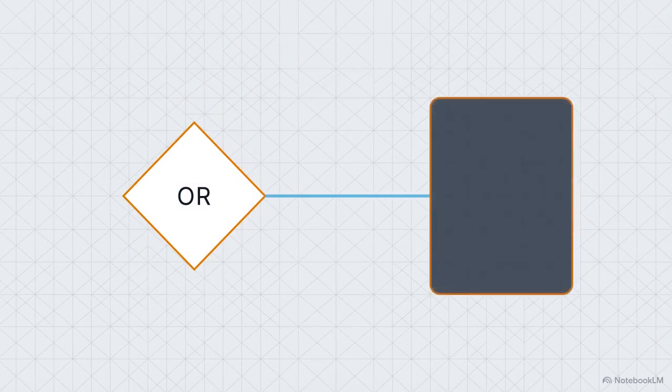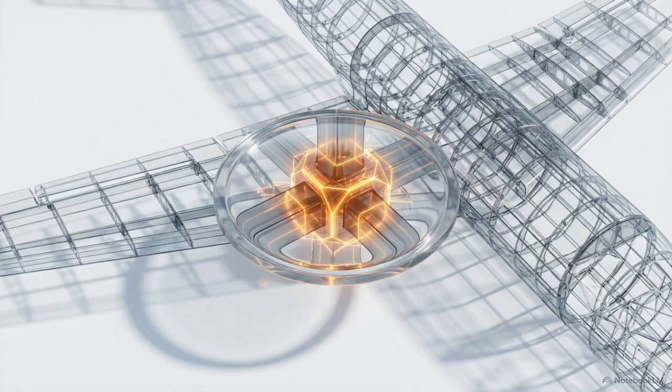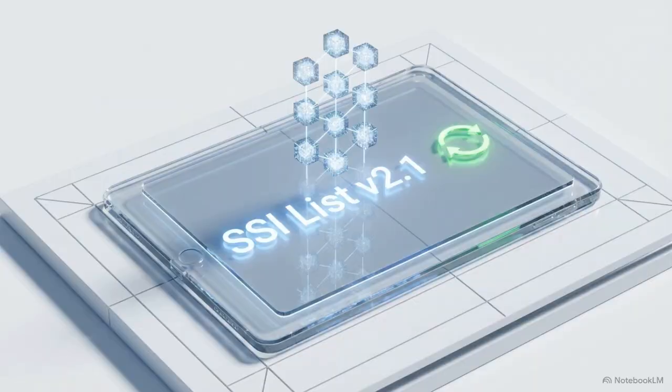If the answer to any of the gate questions is yes, the item must be analyzed as an SSI. In Step 3, these items are compiled into the official candidate SSI list and presented by the manufacturer for review. Step 4 requires the working group to review this list and apply MSG-3 analysis to validate each selected item. This review ensures that no critical items were missed and that the analysis is performed at the highest manageable level of assembly. Because structural requirements can change during the analysis phase, the SSI list is maintained as a living document and referenced in the Policy and Procedures Handbook.